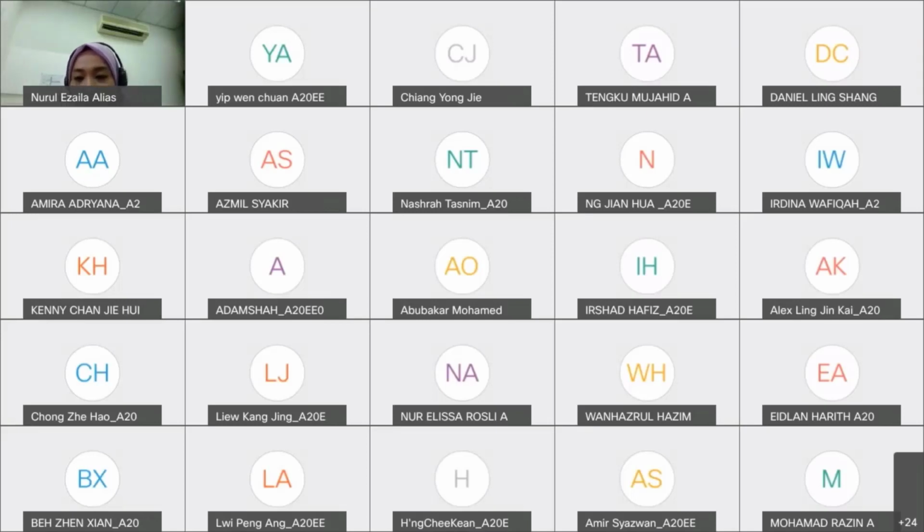Correct. Jinhua, the amount of doping does affect not only the temperature but the amount of doping concentration does affect the depletion region. The more doping of the N type, the more we expect free electrons to pass through. The more free electrons pass through, it actually creates a smaller depletion region. It does affect other than temperature. All right.